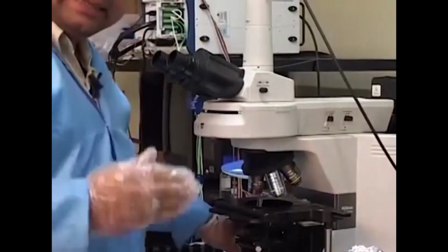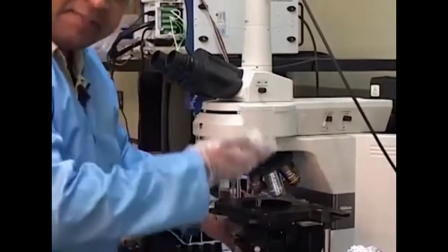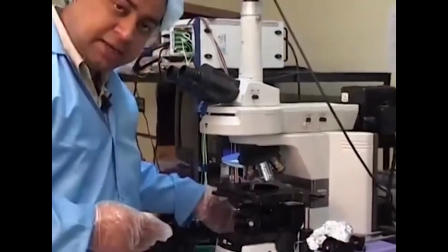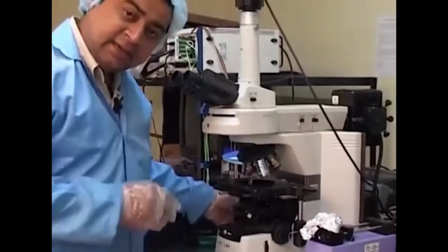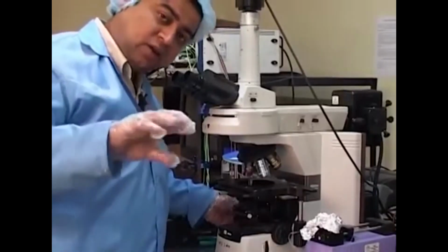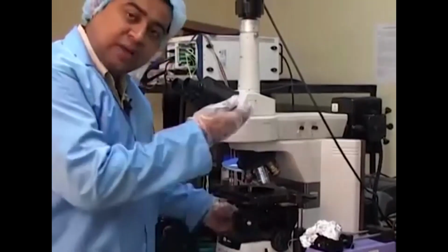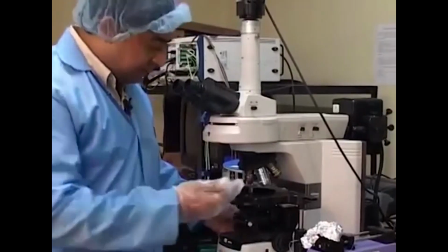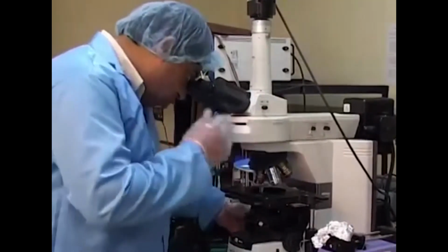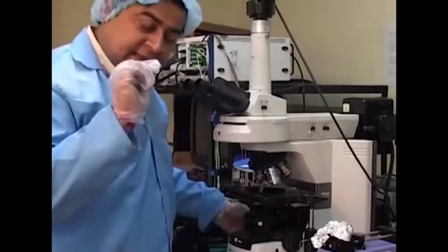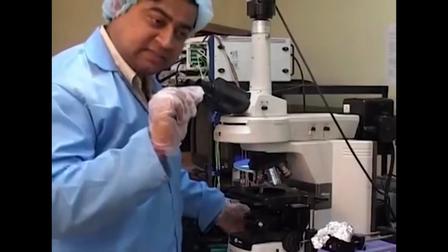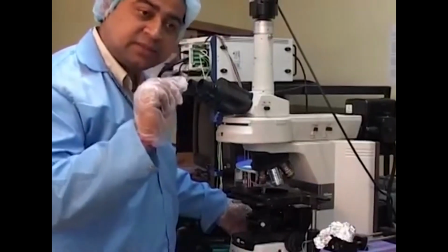The way that you focus these things is by lifting the stage up and down and going in the Z direction. You have a lever here and a corresponding knob on the other side, which you can rotate clockwise or anti-clockwise for the Z displacement to happen in the positive or the negative direction. What you need here is to look into the scope, into the eyepiece, and see at what Z distance the image contrast and the image resolution are the maximum.